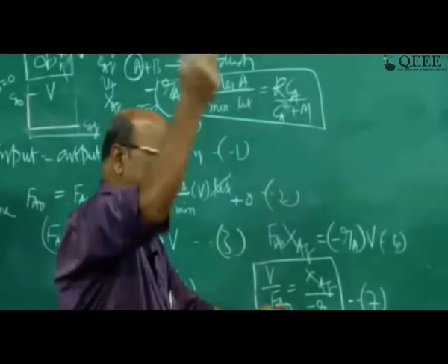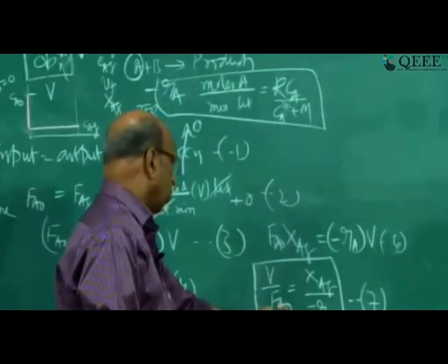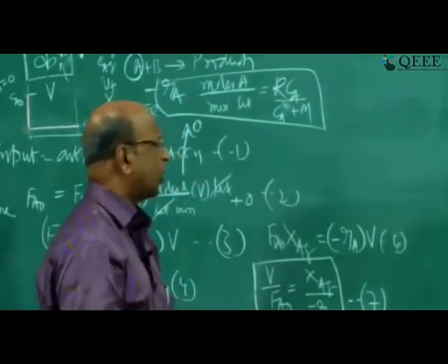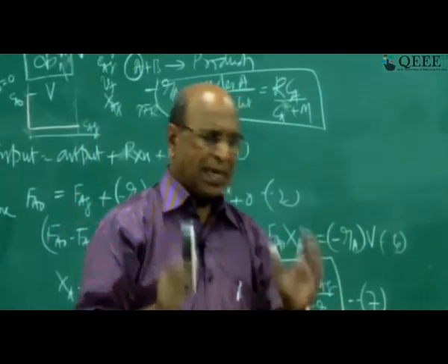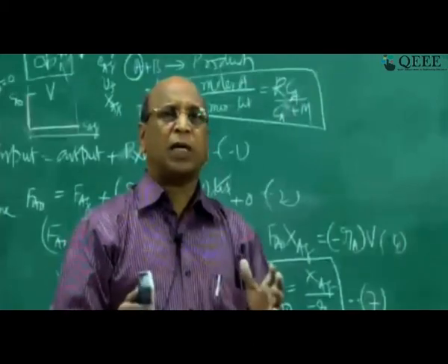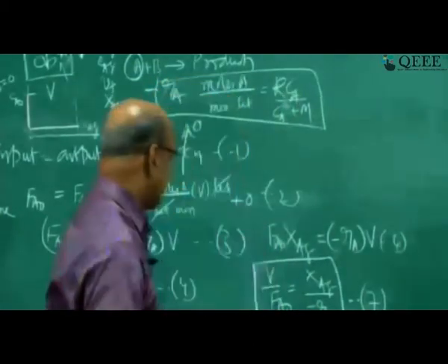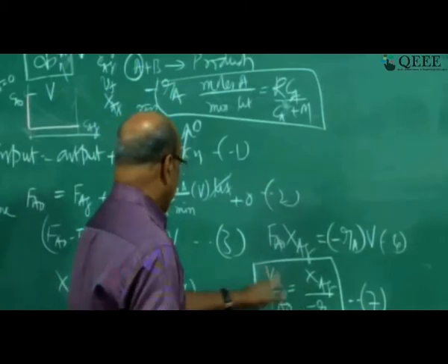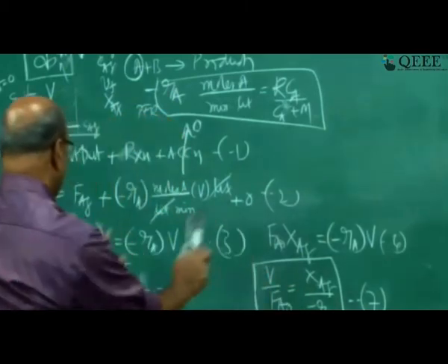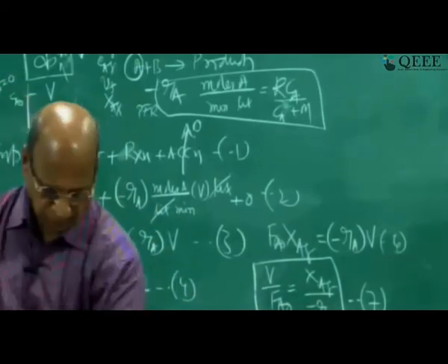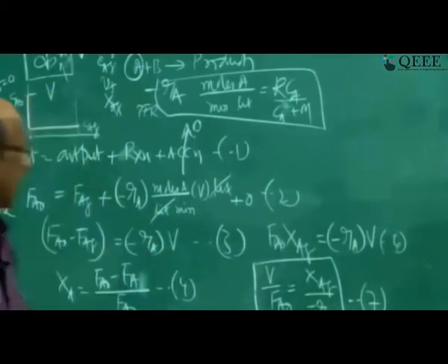FA0 I know, 10,000 tons per day I have to produce, right? And then minus Ra from kinetics I should get. In fact, in chemical reaction engineering, getting the rate equation is very difficult when compared to any other thing, right? Okay, good. So that is XAF. XAF you can calculate for a given reactor. So this is the design expression for the mixed flow reactor.